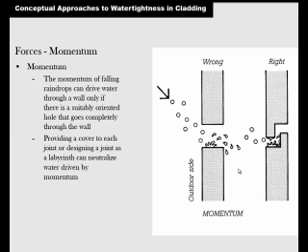Momentum forces are a consideration, shown here in this picture where the droplets will come and bounce in. To fix that, you have this labyrinth, where the water bounces here, bounces there, bounces back. It's very hard for it to bounce all the way up into here. So creating a labyrinth is a better way.